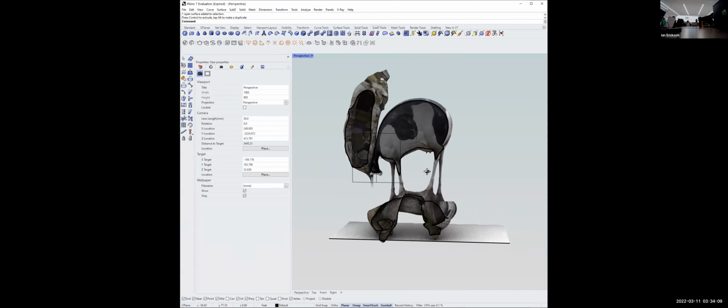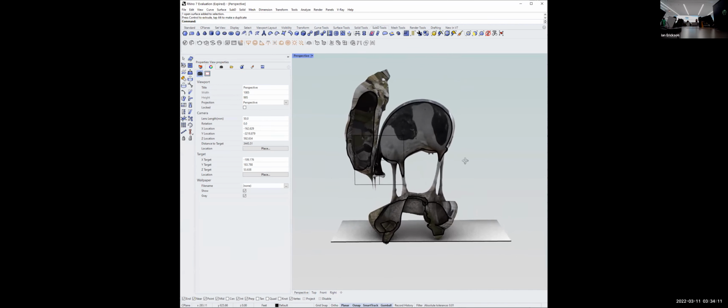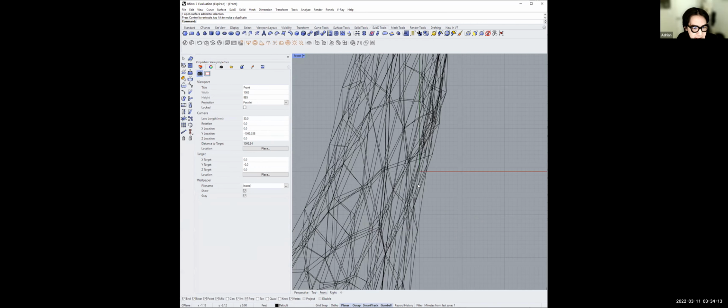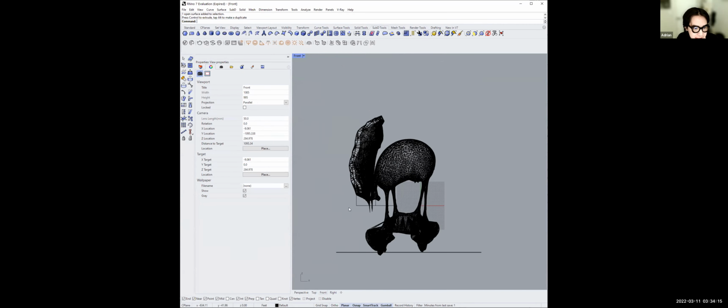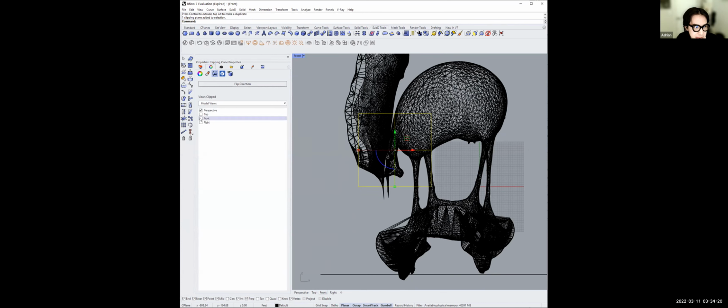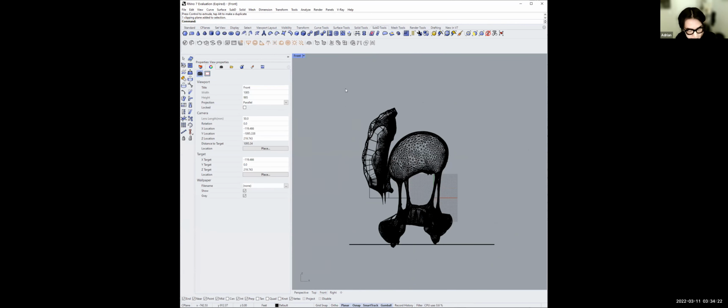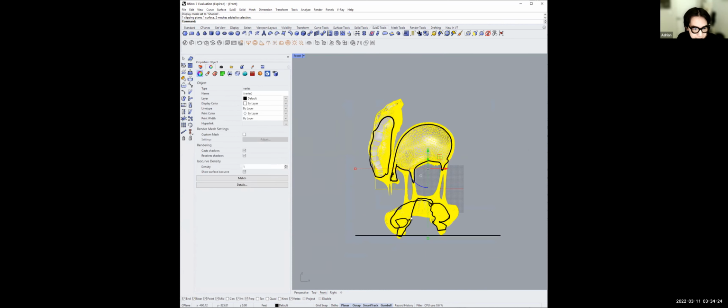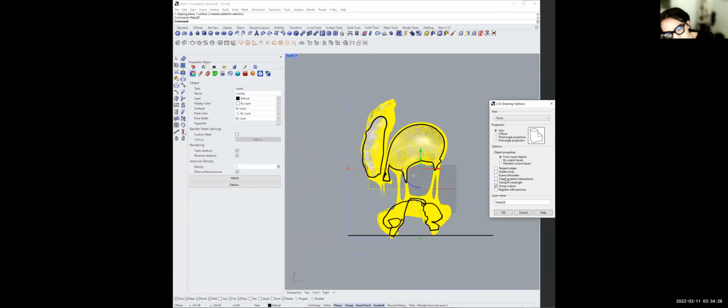Can you make that 2D in an easy way? Yeah, of course. Like as a section? Yeah. Okay. Clipping plane, we're in front view, make sure the clipping plane is set to front. We've got all this stuff, and then we'll just do Make2D. Turn on the clipping plane intersections.